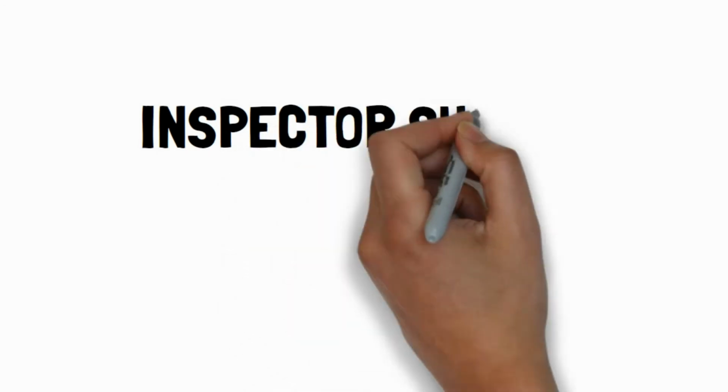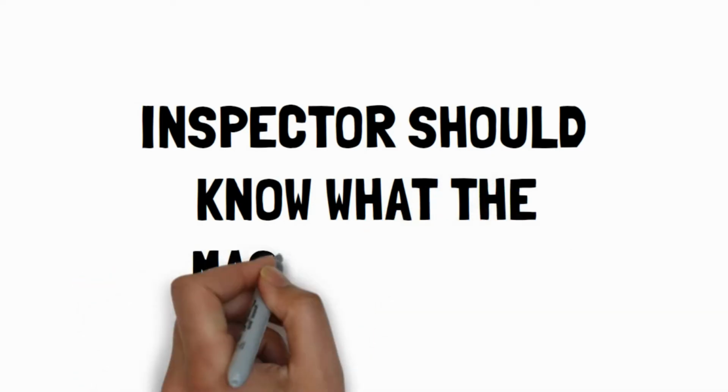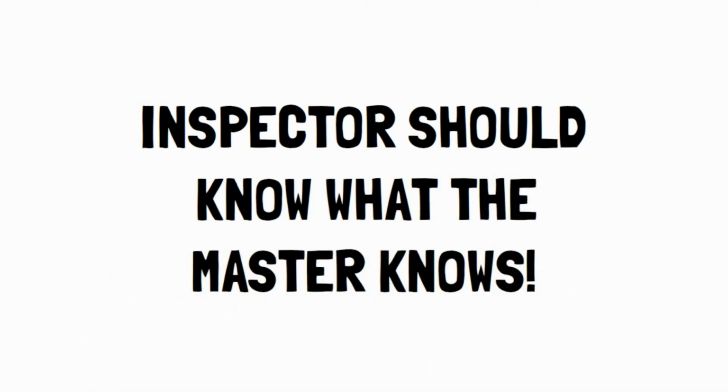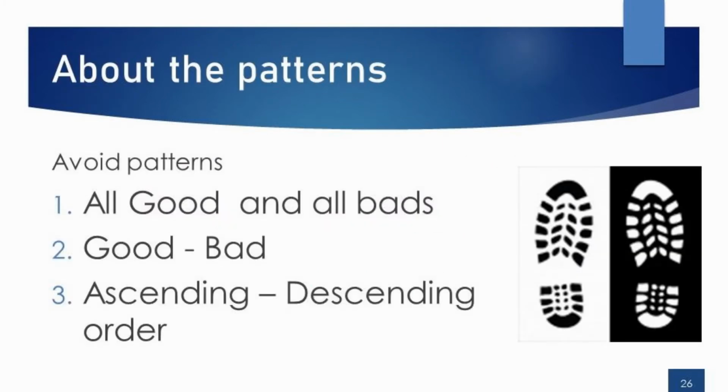We want these inspectors to be like the master. It's like having the master, the customer, the most experienced person right in the spot. So, very important: when you build this master sample for testing, you need to avoid building patterns like all good, all bad, or good, bad, or any ascending or descending order, because especially humans, when they don't know the answer, are going to fill in with these patterns.